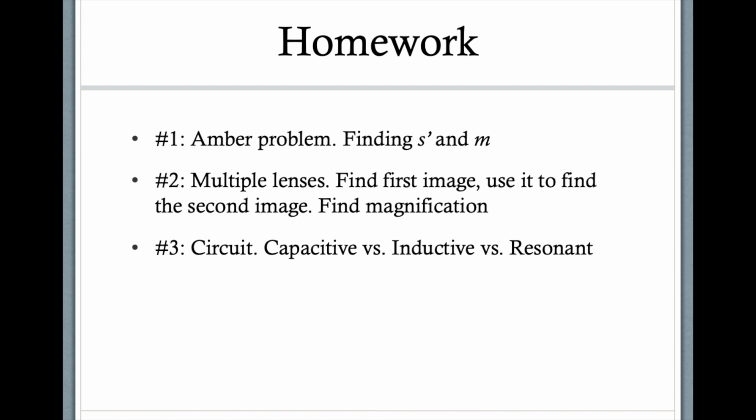In number 3, it's a circuit. You're asked to find whether it is capacitive or inductive. You should use the definitions and go over what we did on the first slide. The second part to the problem discusses how to find the resistance. You want to be able to set up 2 systems of equations and try and see which equations help you find R. You don't want to use equations like the reactance which don't involve R. You want to use equations that involve R explicitly, and then another variable that you can relate possibly to another equation. Remember, you only have 2 equations. You have one equation for the phase shift, so you should use one of the 4 given, and then Ohm's law. So think about it that way.